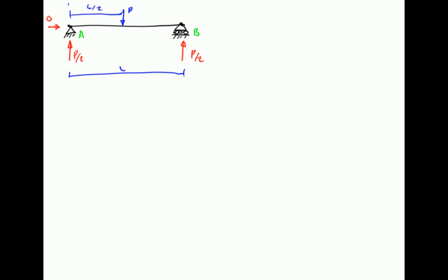Okay, so in terms of structural design, when we come to design a beam like that, we need to know what internal effects those external loads are having on the beam. The principal effects that we consider are axial load, and because we have a rollered support at this end of this beam in particular, there is no axial load. The horizontal reaction is 0, and there are no external loads which give a horizontal component. So the load P that's applied to that beam will give rise to shear forces and bending moments, and we need to know how to calculate those within the beam.